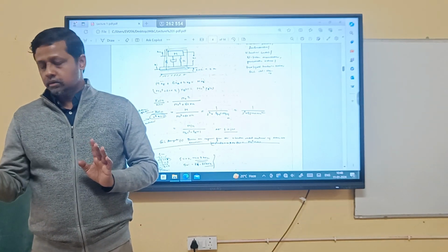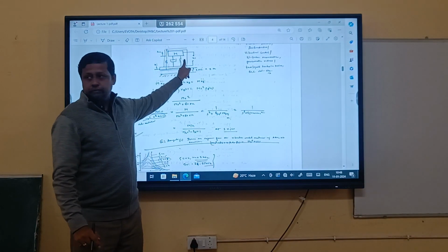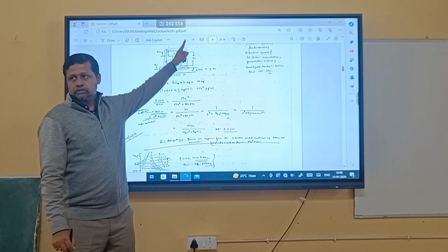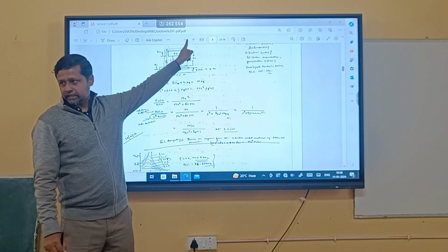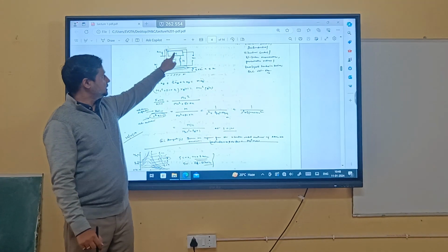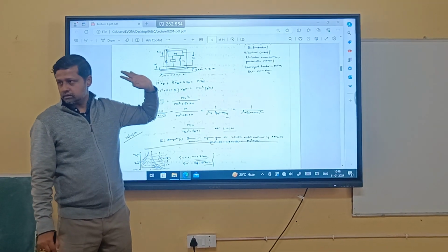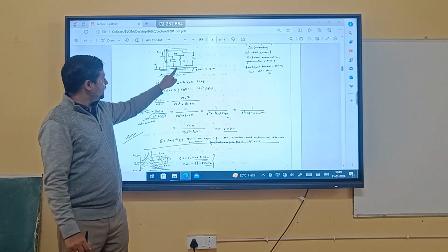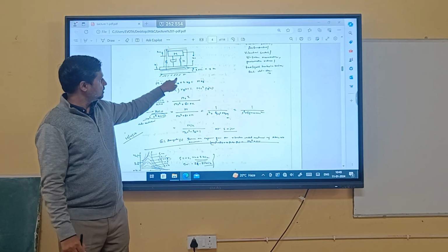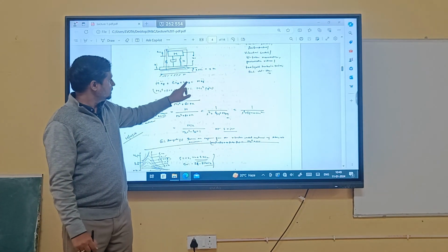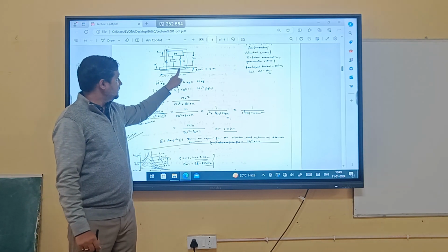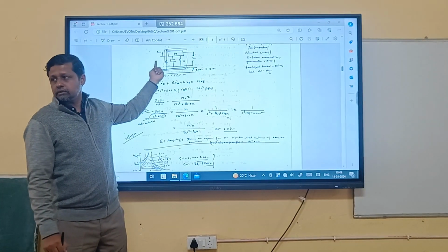So what did you say just now? If x is the input, this part of the system will experience the same order, this part will experience first order, and this part will experience second order. All comprise one device, one system. So you will get this plus this plus this, right? So can I say that m x naught double derivative plus b x naught single derivative plus k x naught same order is equal to, you are getting this response because of this input displacement, or not?